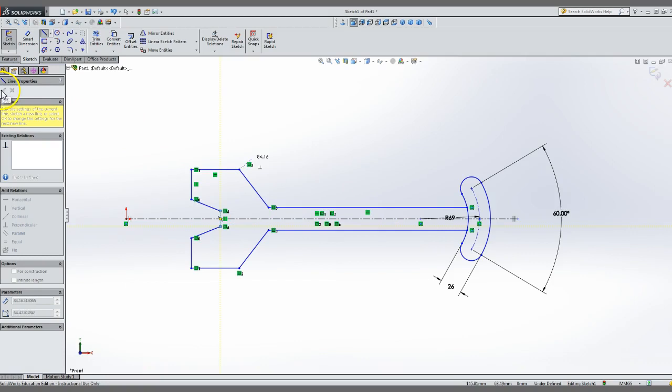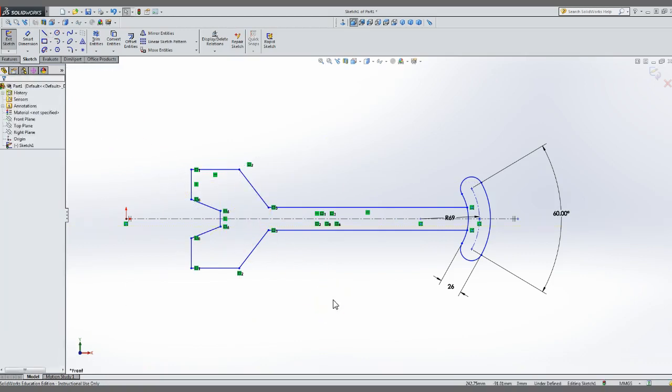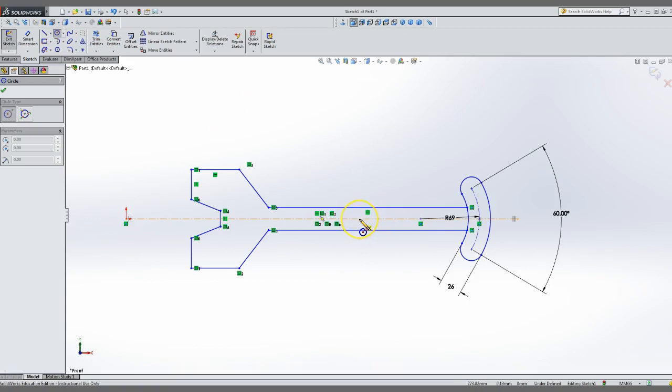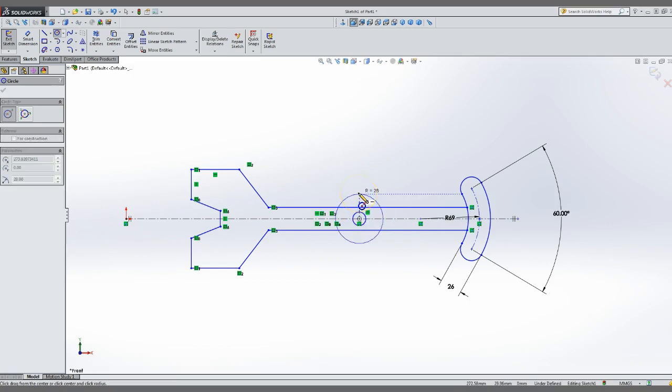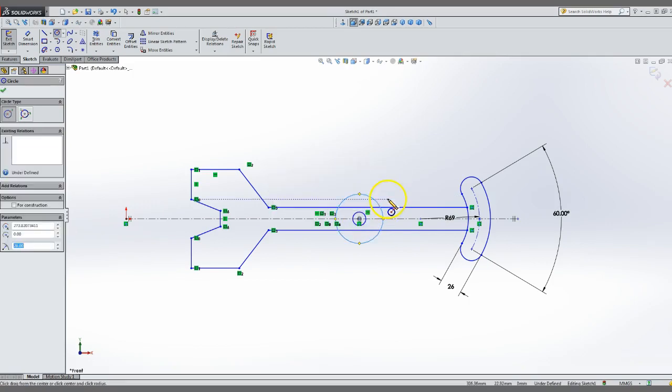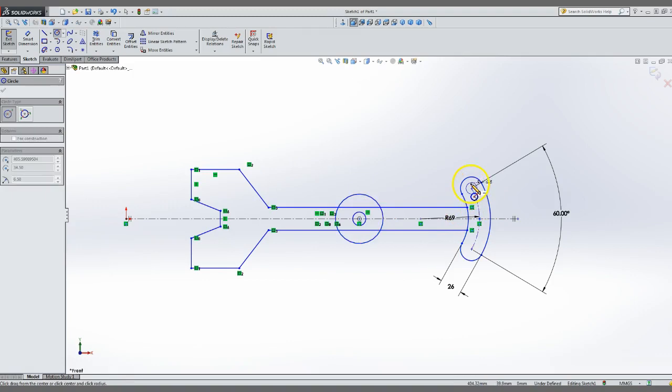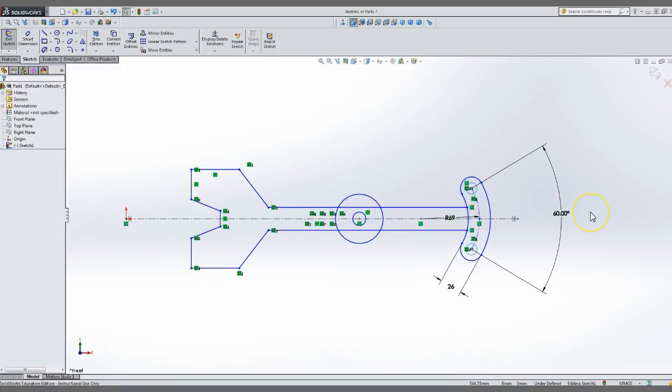Anytime you draw a vertical line like that that goes through that center line sketch, it's going to give you that warning, and that's totally fine. Out here in the center we have some circles, so we're going to go ahead and draw those. One's small, and again, that's fine, and one's large. So sometimes when you get warnings, it's not always a bad thing. So I use that dynamic mirror, and I have my basic sketch done in there.